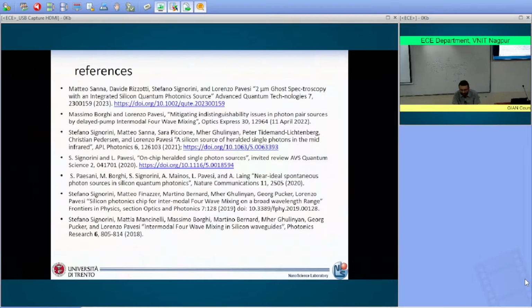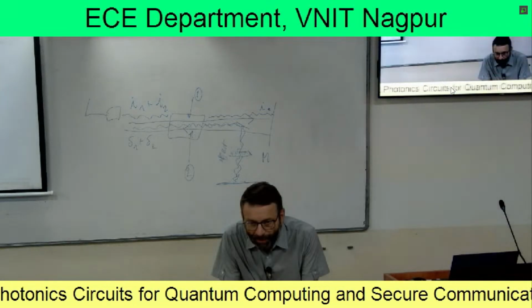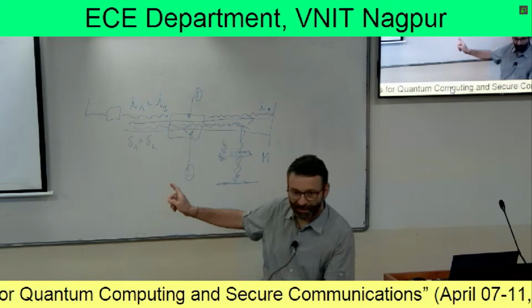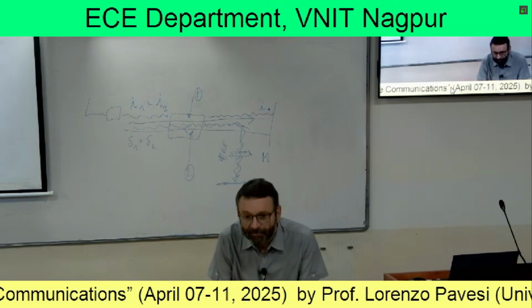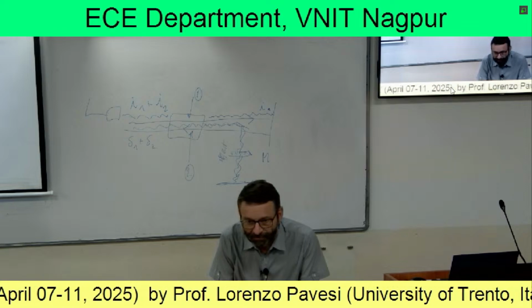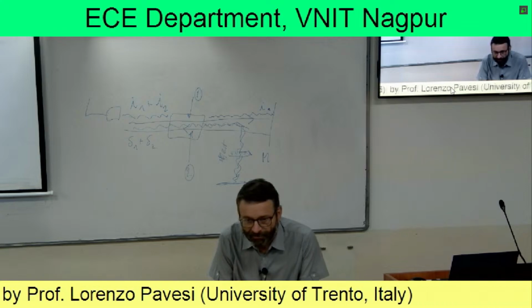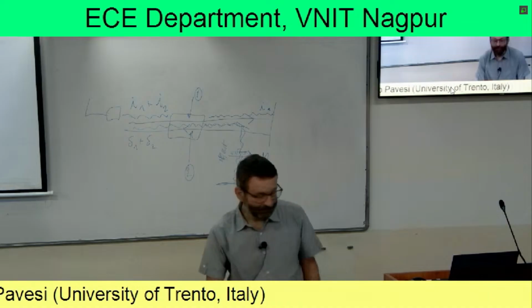Yes. So you have made a waveguide width of somewhere around 500 nanometers. What is the waveguide width in this multimodal waveguide? 2 micron. 2 micron. Okay. And you also have a sidewall, right? So does the roughness of the sidewall affect the experimental results in some way?